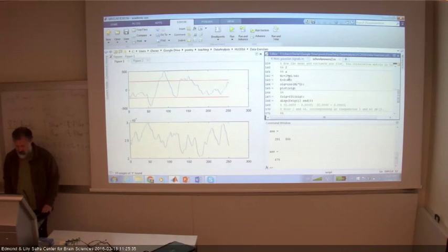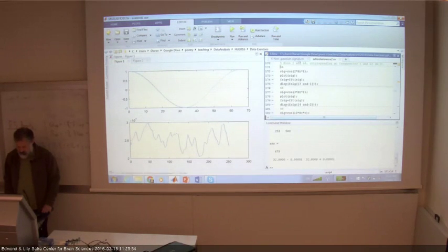Exercise number 2. So I wanted the sine cosine sampled at 64 Hertz at 1 Hertz. Here it is. I calculate the FFT. This is what we did in class. The relevant bins are bin 2 and bin 64. Both have a complex number which has an amplitude of 32 and a phase of 0. You see the imaginary part is 0 in both cases. Everything else is 0. I'm not going to dwell on this.